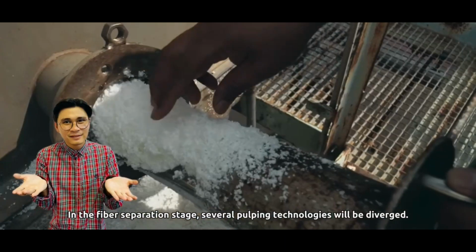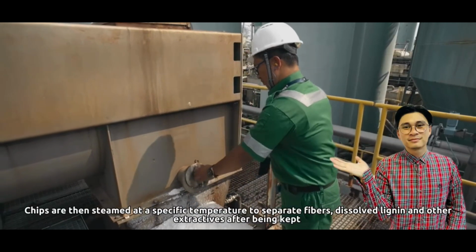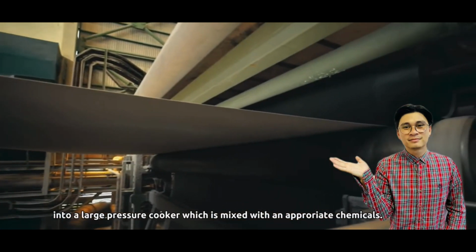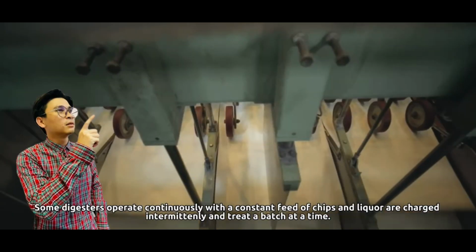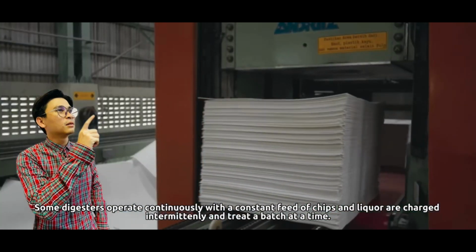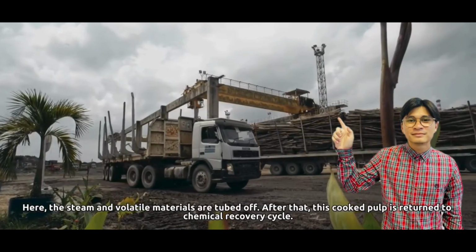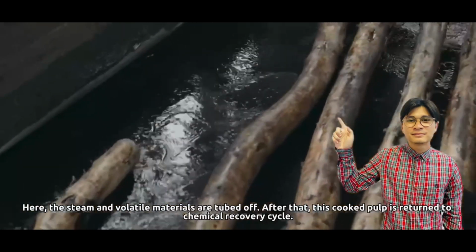In the fiber separation stage, several pulping technologies are used. Chips are steamed at a specific temperature to separate the fibers and dissolve lignin and other extractives, after being kept in a large pressure cooker mixed with appropriate chemicals. Some digesters operate continuously with a constant feed of chips, and others are charged with liquor intermittently and treat a batch at a time. After the digestion process, the cooked pulp is discharged into a pressure vessel. Here the steam and volatile materials are tapped off. After that, this cooked pulp is returned to the chemical recovery cycle.